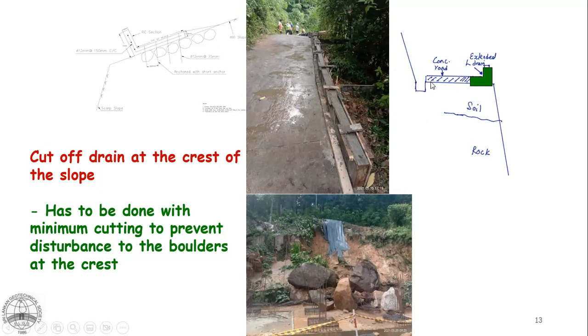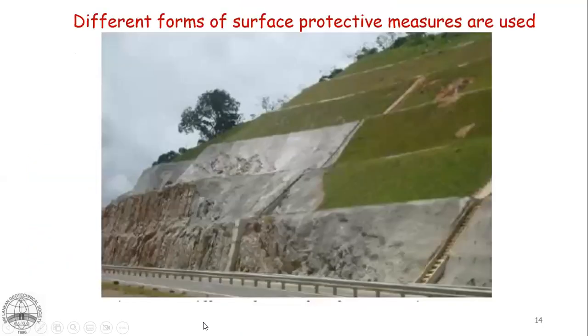There was the side drain of the road on the other side. So there is no water flowing into the steep slope, right? The steep slope. So that is the condition. There's some soil thickness above the rock. So that is vulnerable. So water was not allowed to move into the sloping ground. It is intercepted here by the cascade drain. So we have to think of the site-specific situations and come up with the most appropriate surface drainage solution.